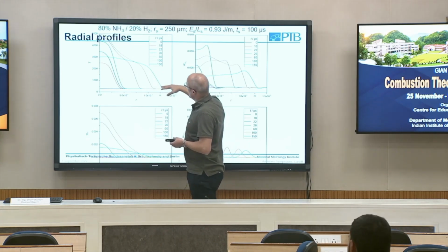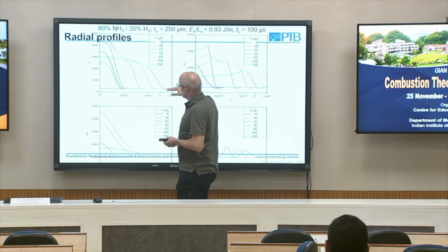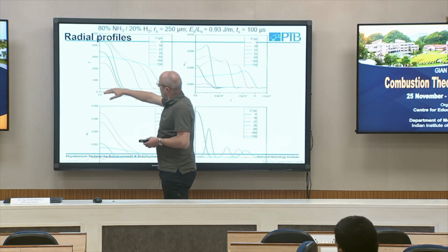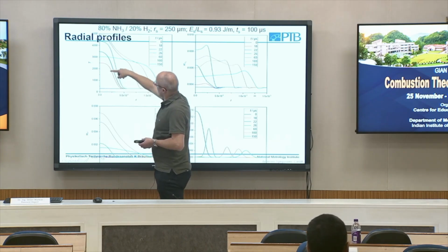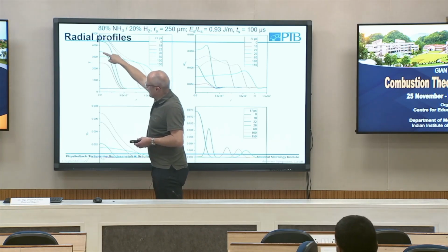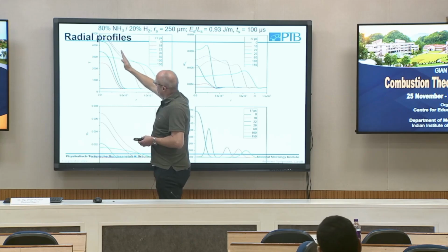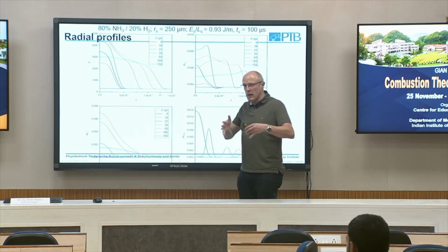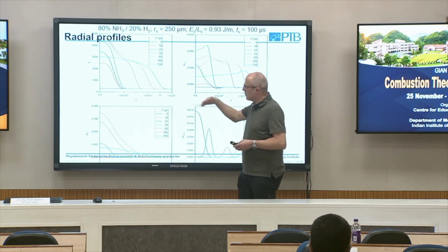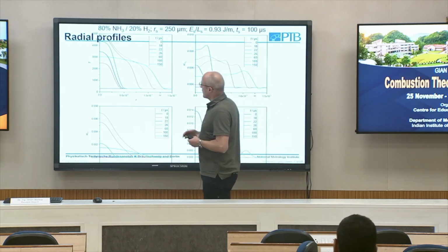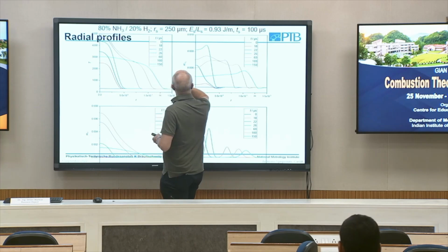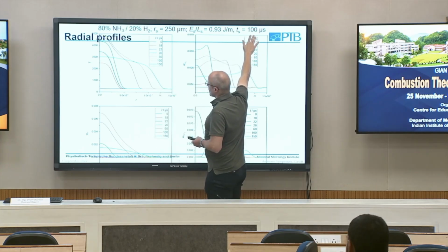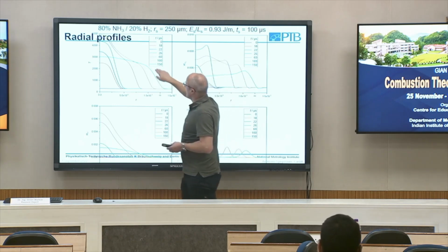And here we have the temporal development of temperature. So at the beginning, of course, 300 K. And then we deposit some energy. It heats up, and then the flame front moves away from the hot spark channel into the unburned gas mixture. And the length of the energy deposition is 100 microseconds.